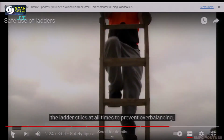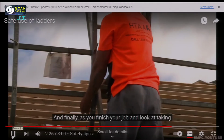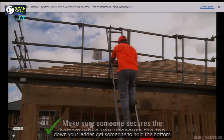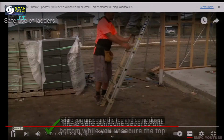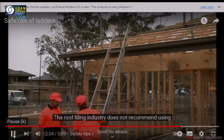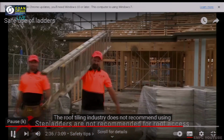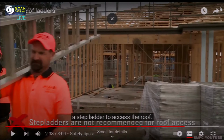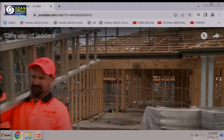There is a use of a buckle belt, because in case a person has a tendency to overreach, it is better to have a lanyard or a buckle belt so that people know that they should not be overreaching beyond a certain point. While finishing the work, it is also better to have someone support you from the bottom during the dismantling of the ladder once the work is finished.